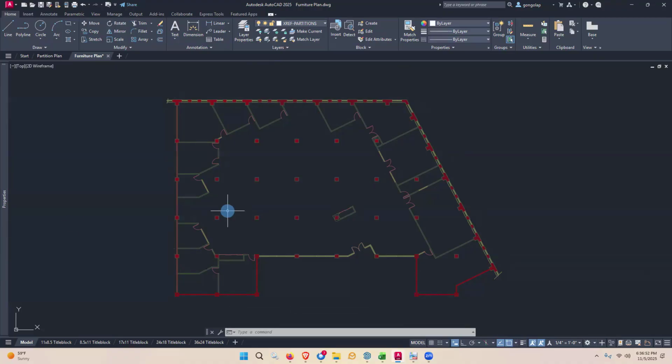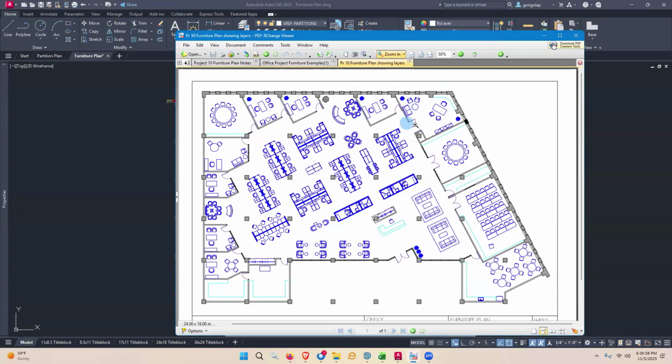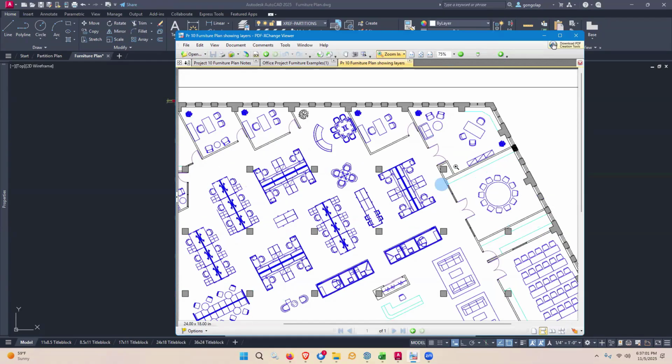All right, let's see. Where shall we start? I'm going to start in this executive office over here. He or she has got a big desk over here, and then a built-in credenza back here. I'm going to start with the credenza, and then I'll move to the desk. So I am going to add this on a millwork layer. This is shown in cyan, but I think our millwork layer is yellow. Traditionally, I think it's yellow. And then I'm going to put all the furniture on the furniture plan here.